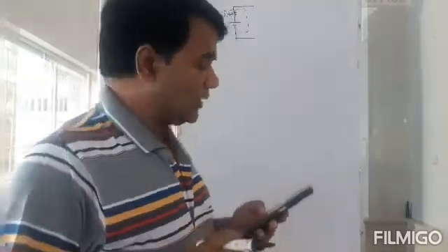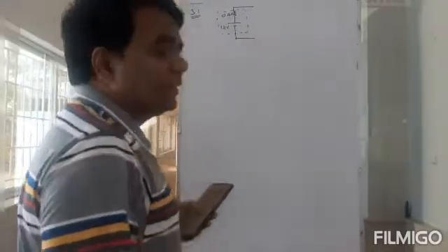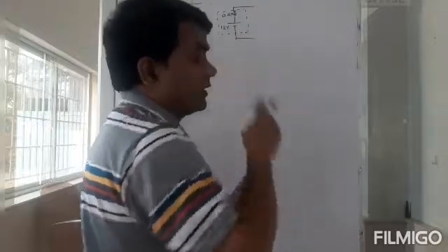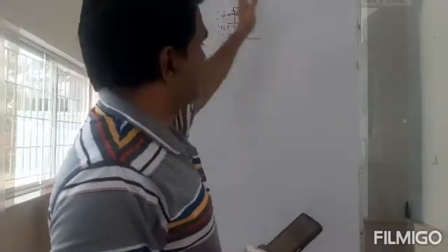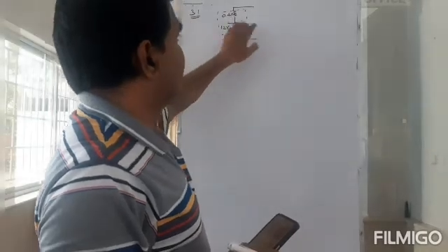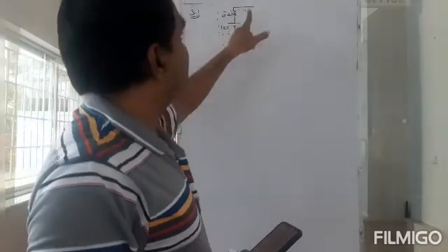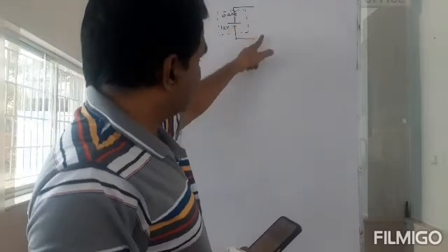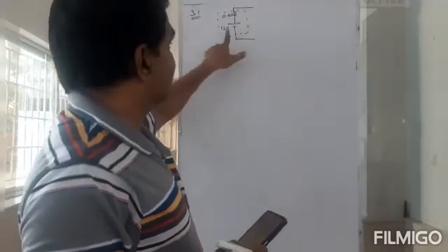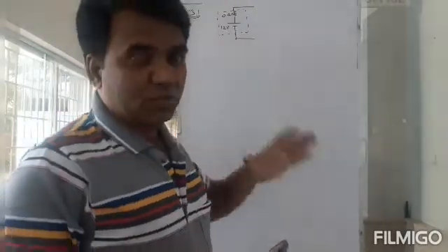So when can you draw the maximum current? When you short circuit it. When you connect these two ends, then there is no resistance connected there. So then the maximum current will flow through it. Suppose that there is no resistance here too. If 0.4 ohm is not the resistance, then the total resistance in the circuit would be 0 ohms. So then the current would be infinite, if this internal resistance were not present.